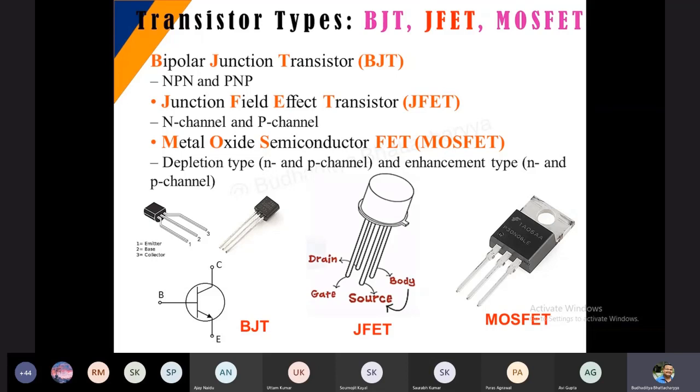You keep it towards you, so that by keeping it towards your face, the leads 1, 2, and 3 stand as emitter, base, collector. That is how it should be read properly. Otherwise, the emitter, base, collector connections will be erroneous, and hence the output won't come. The symbol for this kind of BJT is usually of this nature, and we will see that later on also.